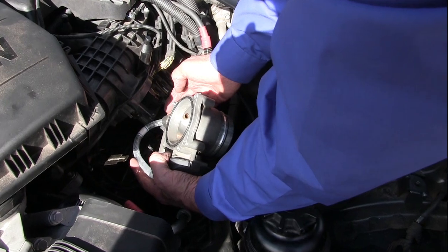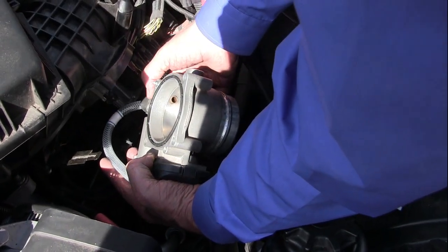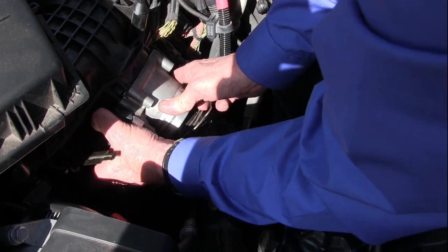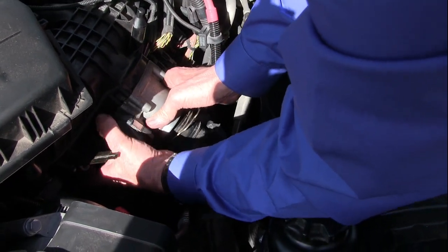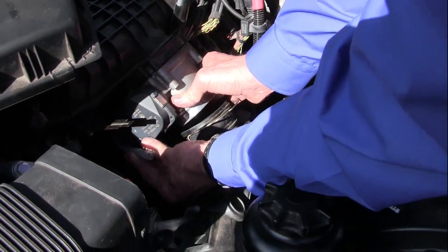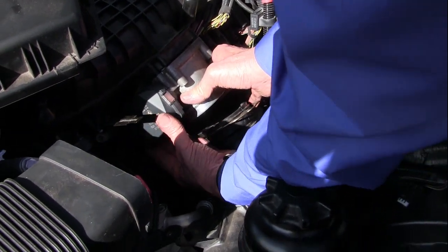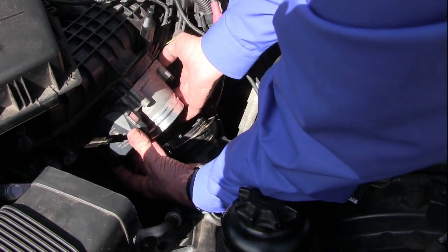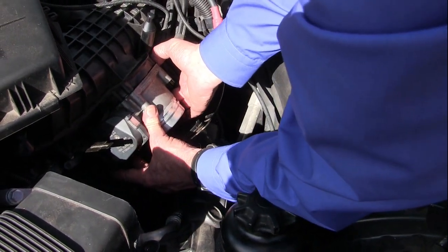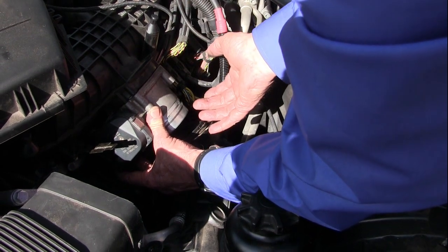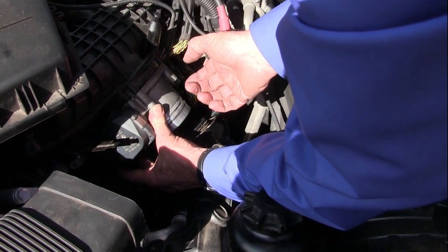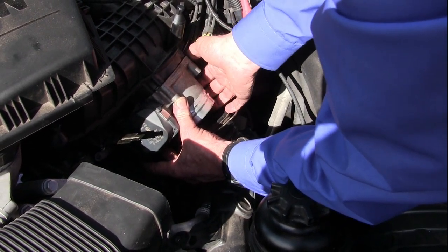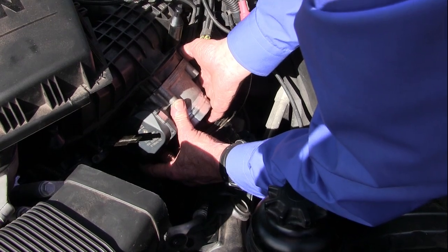Now that we've got the ATS approved hose onto the fitting, we're going to go ahead and put this throttle body back on. The hose will stick out over here on the side, and it will allow me to put the injector onto it. Just put 2 bolts crosswise for right now, and then do the cleaning, and then when we take it back off and we reassemble it for the final version, then we'll put all 4 bolts on. 2 bolts will be good enough on here for right now for the cleaning procedure.